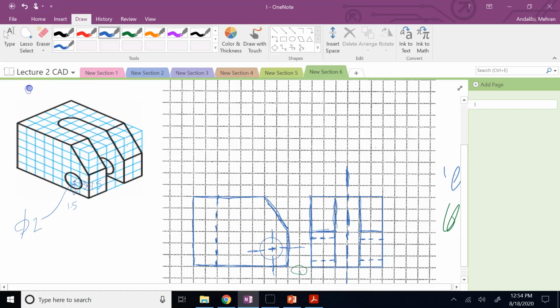Finally, top view. Again, we have to stay here and look down on the front side. So I would see this C plane and these two basically smaller than real size. Again, I cannot see the holes. So the same 2 unit gap I had between front and right, now I leave between what? Between front and top, and I would start drawing.